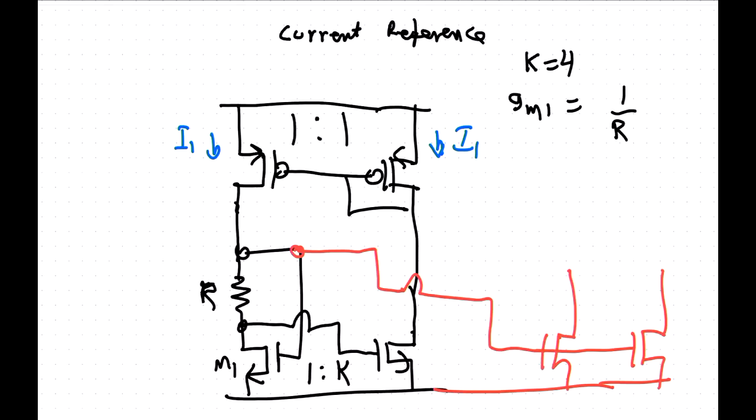So normally with this circuit, you have to put in a startup circuit. You've got to detect the condition that there's no current flowing in this. We've got to do something about it. You can do it in many different ways. One way you can do it is you can have a PMOS device here that is always on, but it's very long.